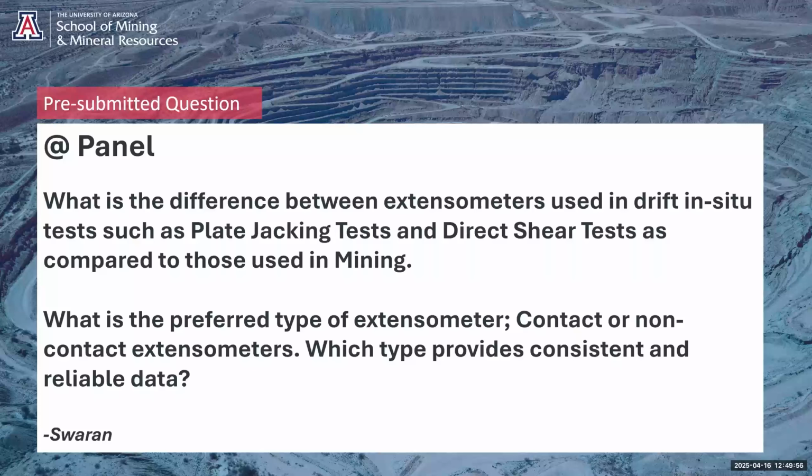Anyway, the laser light size that you would have at the borehole would probably be larger than the diameter of the borehole. So that would have an influence on the accuracy of the measurement. So bottom line, I don't think there are non-contact laser type borehole extensometers yet on the market.